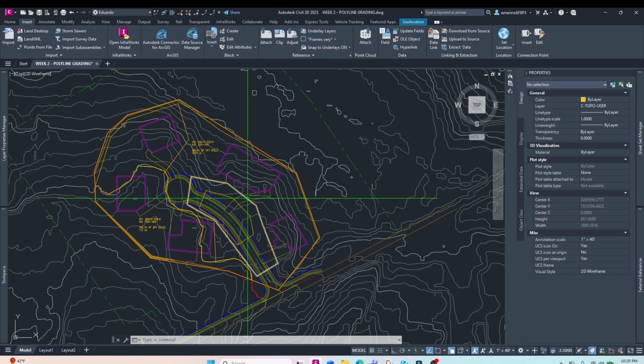People do this strategy, which is what I've been saying, matching the road to the existing ground, and just run with it and have all the feature lines set up, all the corridors looking pretty, the profiles looking nice. You have feature lines, grading groups, everything is detailed out, and then you check the earthworks and you're way off balance. And what's going to end up happening, you have to redo a lot of work.